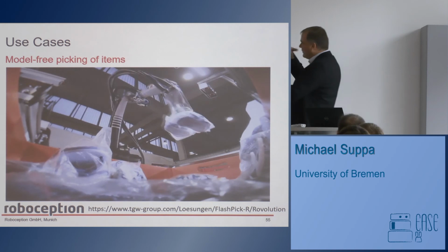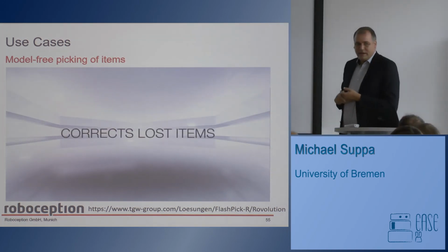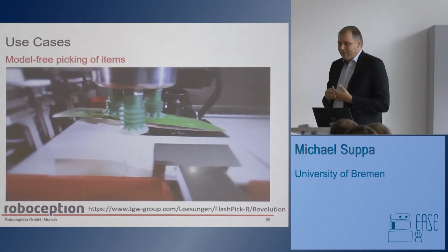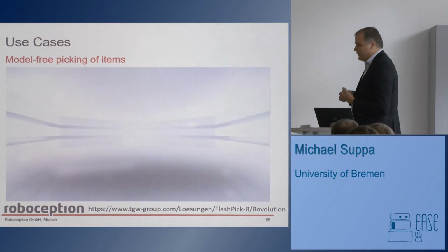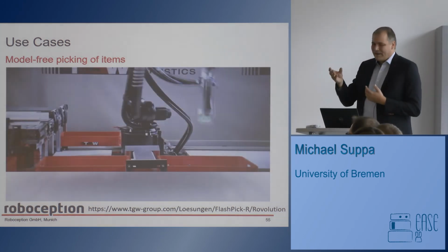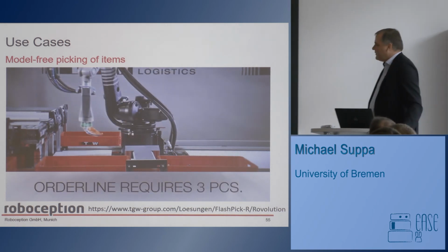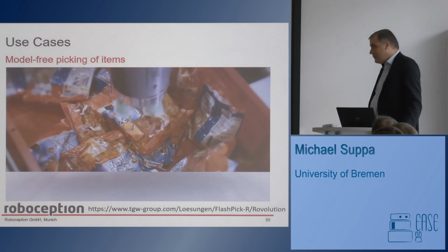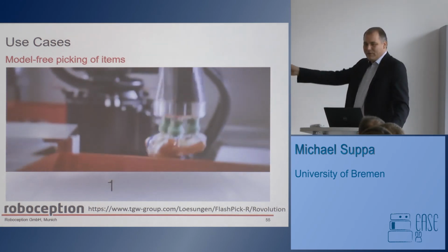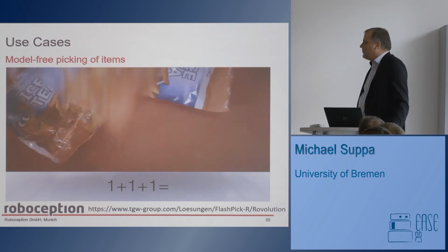You can see our cameras are mounted on top of that, and also static cameras help. If you have your camera on the robot, it's slow. When you have to move the camera, take the image, move on, that's basically slow. So this is why in most of these applications, when it comes to picking time, cameras are external, because you can check on the scene when the robot is moving the part. This really speeds it up.